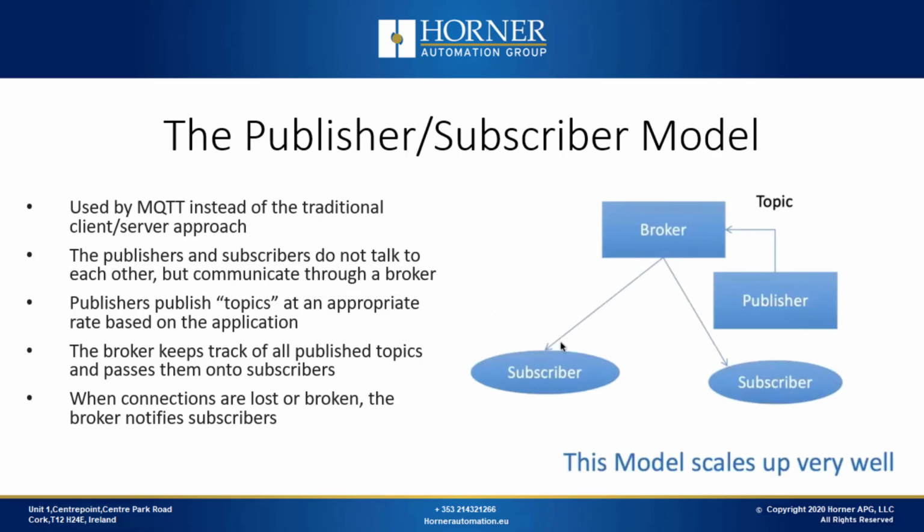The data that's published is called a topic, and it is published at an appropriate rate based on the application. The role of the broker is to keep track of all published topics and distribute them to the subscribers, and when any connections are lost, the role of the broker is to notify any subscribers that the data is stale or the connection has been lost.